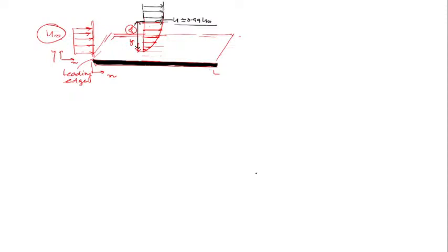So as I told you, the velocity here is u equal to 0, and nearly the upstream velocity we are getting only in the delta thickness of the film in the y direction. So most of the gradient lies only here. Beyond that there is no change in the velocity. Velocity is uniform here, you can see uniform with the velocity of u infinity. It means all the change, or the gradient, will exist only in the smaller region close to the surface, and that's called the boundary layer region.